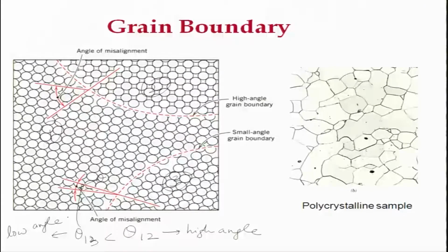And if you look at the grain structure of materials in an optical microscope, to visualize this, you need to normally subject the material to an acidic treatment. Okay. So, which is called an etchant, use of etchant. So, basically this etchant is nothing but a mixture of a few dilute acids, which preferentially removes the atoms from the grain boundary area, because grain boundary is a loose part of the material, it has higher energy.